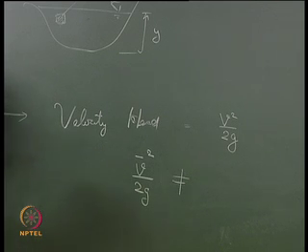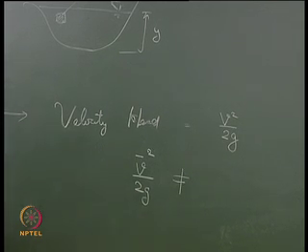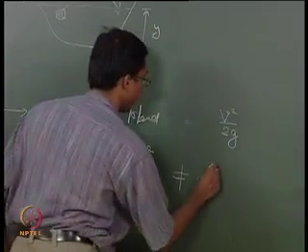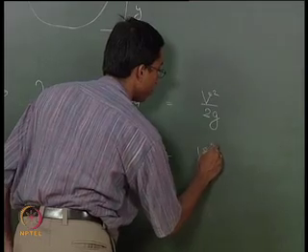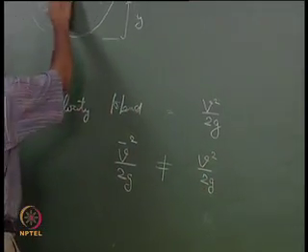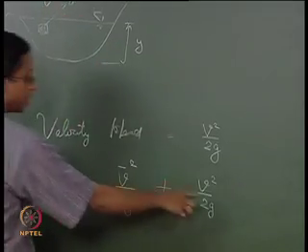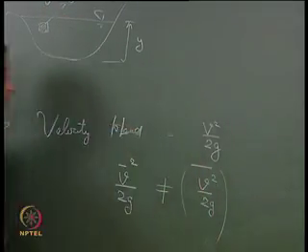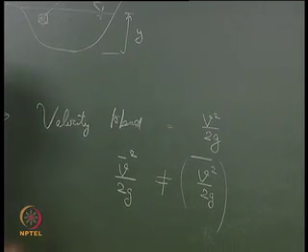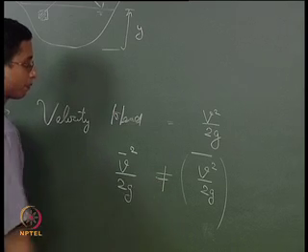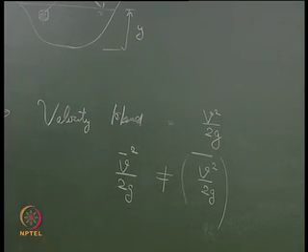That is what is seen in many experimental studies. So, we can suggest now that if I take v squared by 2g for the entire cross section, and take the average of this quantity, they are not equal. To correct them, we may have to use a correction factor.